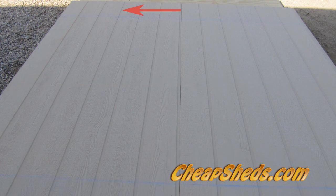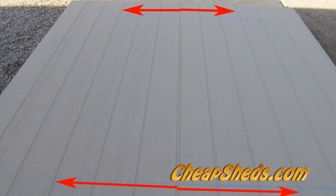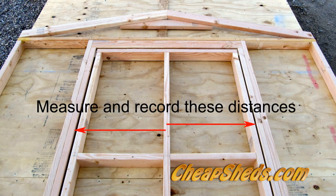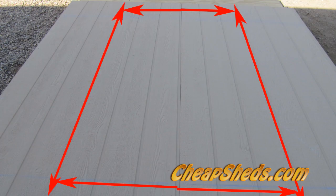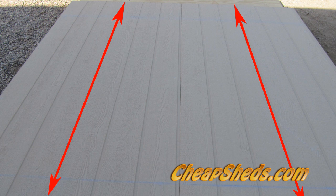For 8 wide sheds, place a pencil mark at the top and bottom of the siding 22 1/4 inch from the middle of the center stud in both directions. This should be half the rough opening width plus 1/2 inch in either direction. This is the 21 3/4 inch measurement you took above just before you nailed the first piece of siding. Do the same type of calculation with the different door stud locations if you are building a 10 wide shed or if you're changing the door location. Snap a chalk line on both of these marks. These are the 2 vertical cut lines.